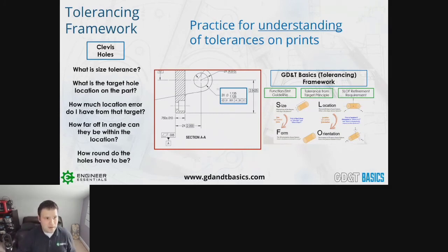That's the perfect target. But then we're saying, okay, from that perfect target, basically from where it should be in the CAD model, you can be 1,000th off, and that's 1,000th in diameter. So you can actually only be 0.5 in any direction. But you have a total variation of 1,000th, basically 0.0005 up, down, left, right, at any angle in any direction. But geometric tolerances are always total tolerances, so they're always specified as a diameter, not a radius, just so that you're aware.